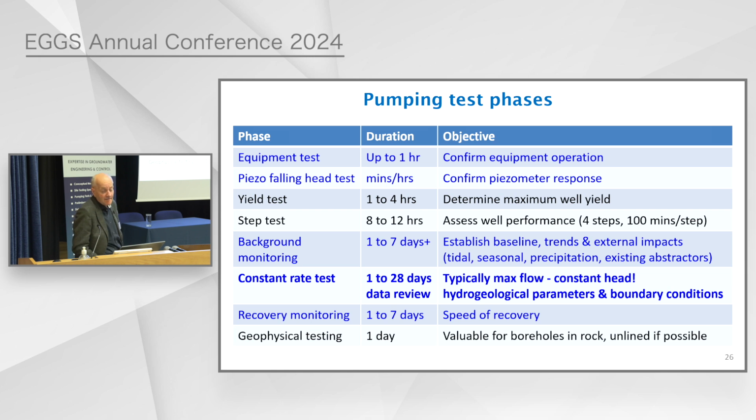Having said that, yes, I like step tests. They don't take long. I think they are generally worth doing, but I don't think they're essential. Background monitoring, absolutely essential. And you certainly need a few days to make sure you understand what trends, and preferably longer.